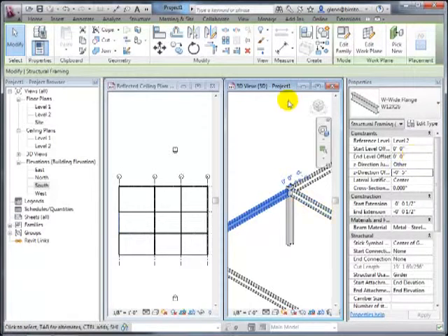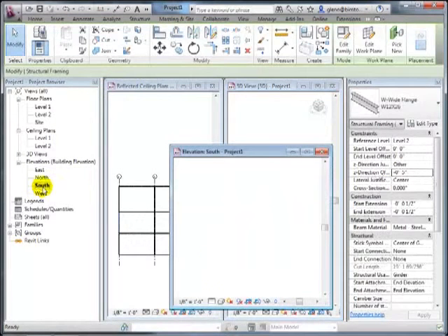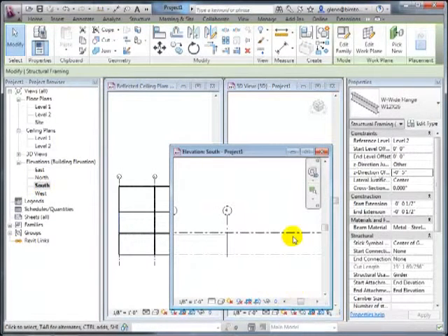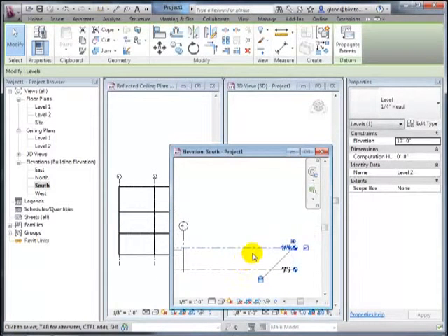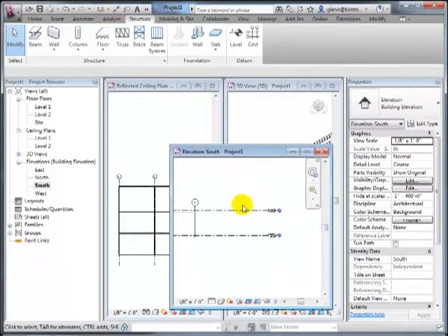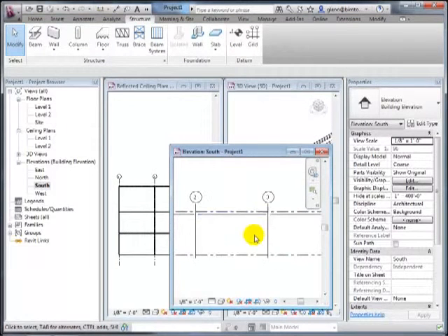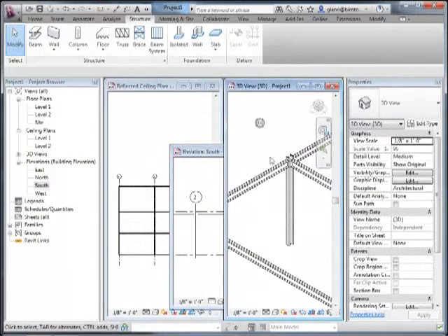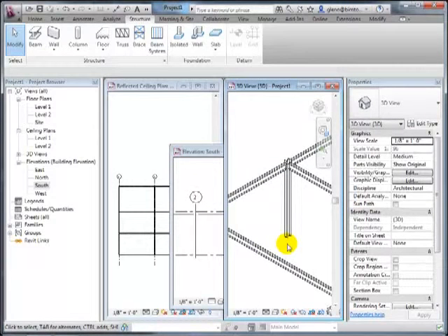For example, to your point, if we're partway through the construction and someone tells us that, to really accommodate what we need in here, we have to have a 15-foot floor-to-floor level, what's going to happen is everything is defined relative to that level. So the columns got taller, the beams got taller, everything got taller relative to what it needs to be. If that was still on level 1 and you did that same function, it would have moved it. Exactly, because 10 feet above level 1 isn't the same thing.